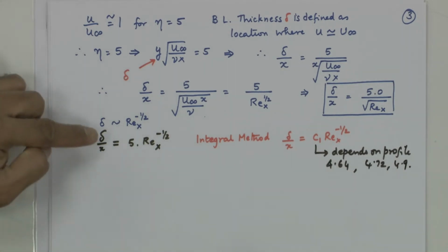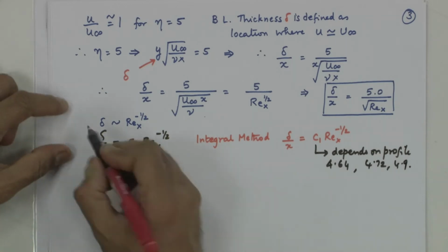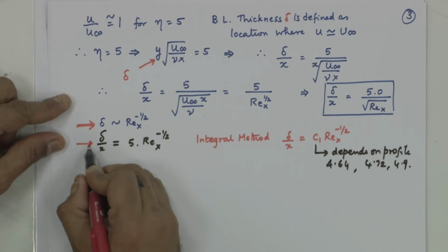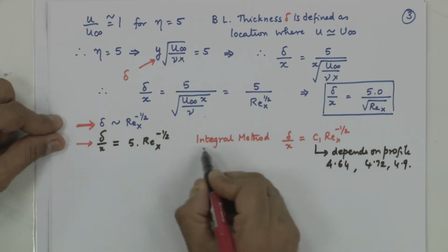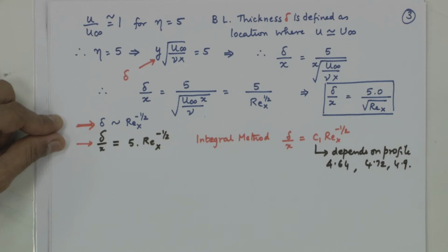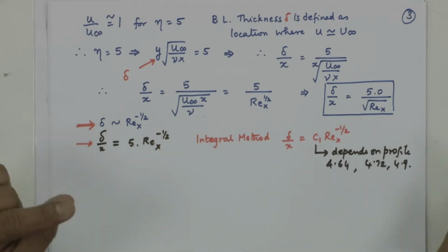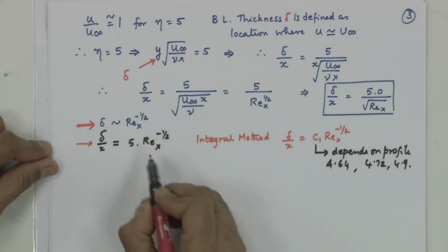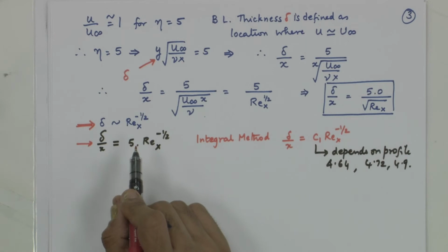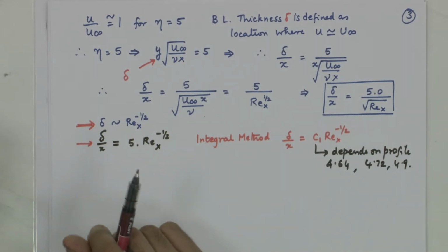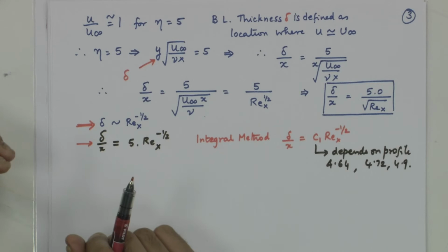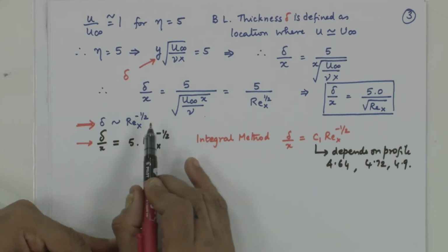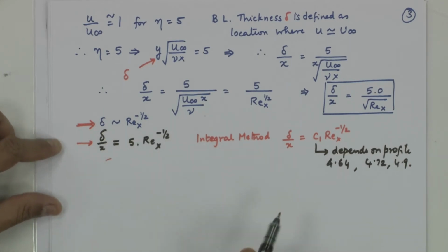And who gave us that for the first time? Scaling analysis gave. So, this was great. This is betterment to get you numbers. This is also another method to get you numbers. So, the point to note is scaling analysis was a tool for me. If I didn't know this functional form, I would be groping in the dark and I would not know how delta is going to vary. Now, even before I go and solve a differential equation or assume a profile, I know that delta has to vary this way. I know the nature of the solution. That is the beauty of scaling analysis.